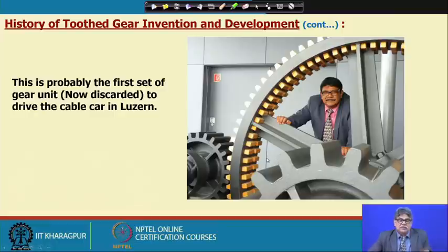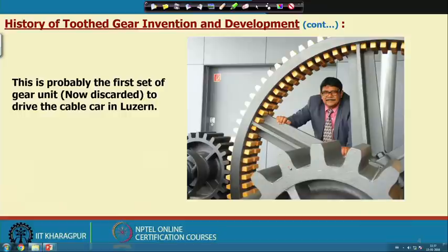If we notice this part, it is looking slightly undercut, but later we will learn that for this number of teeth undercut was not necessary, and probably to give more clearance, this tooth shape looks like that, but it is very close to involute. And these gears were initially cast with this tooth form, and then probably also milled to get the shape.